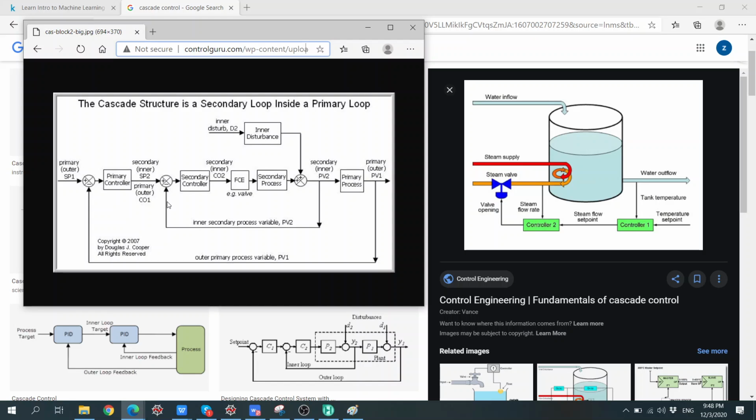If they say we need to have more steam, that means we need to increase the steam flow rate. To increase the steam flow rate, it will have to open the valve, so the steam will then flow through the system. So we have a higher flow rate of the steam in this circle. So this is then a slave control. This is the master control.